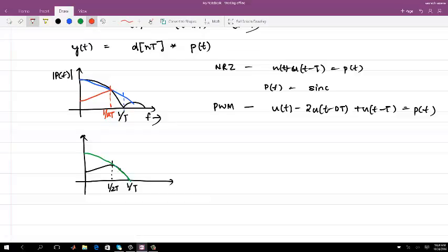where you see that you are not actually equalizing beyond Fs by 2. Whereas for PWM, you can have a similar response passing through the same point but having a wider frequency extension. You have more emphasis even beyond Fs by 2, which is not there in the case of NRZ pulse modulation. So in this case, PWM actually wins.